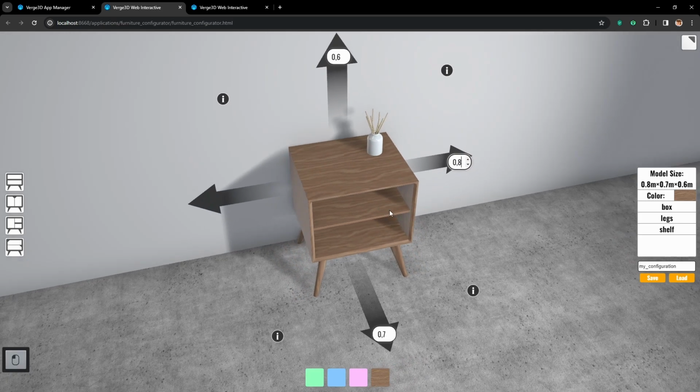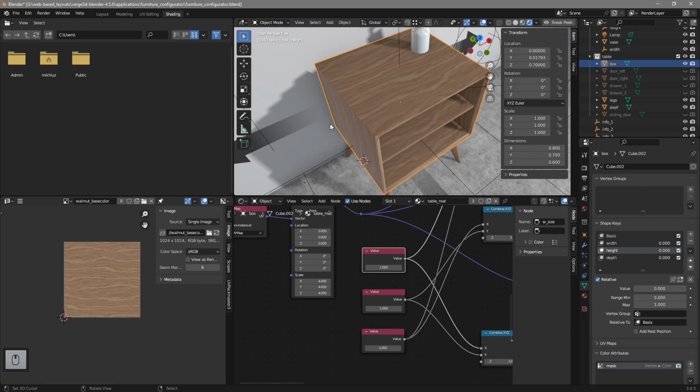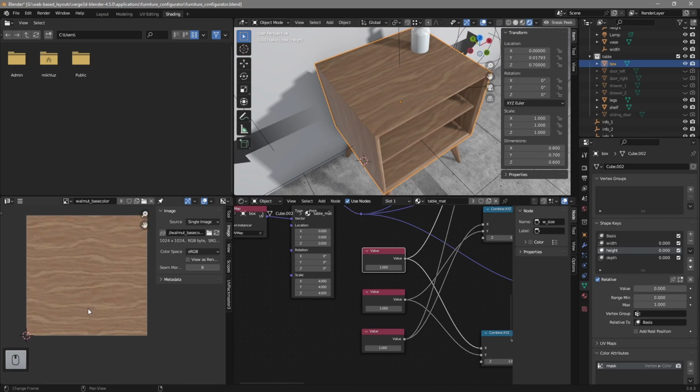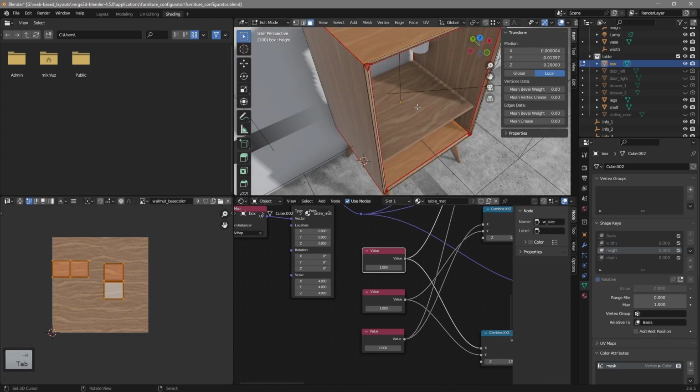However, the texture is visibly rotating or sliding along the geometry, and this behavior is connected to UV mapping itself. UV coordinates start from the left bottom, and then rise up and to the right, diagonally. That means that the center of scaling is in the left bottom corner.